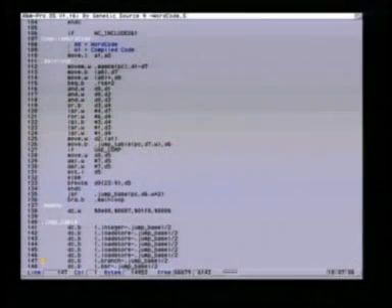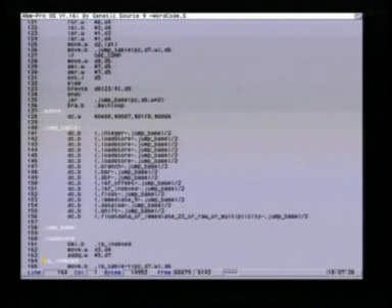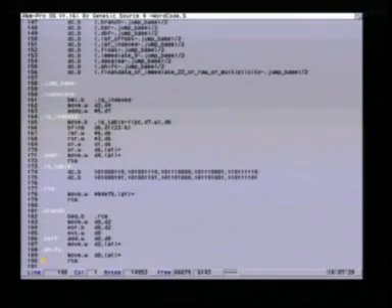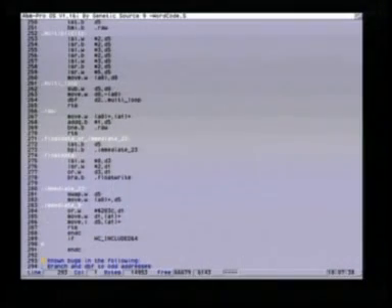So here it starts. The first piece of code, which is on the screen here, is reading in the instructions and taking out all these different bit fields, putting them into different registers so they are ready to be used. And then there's this jump table down here, switching on the first 4 bits. And then it just jumps into different places, which puts the bits in the right places. So that's it. It's not bigger than that.